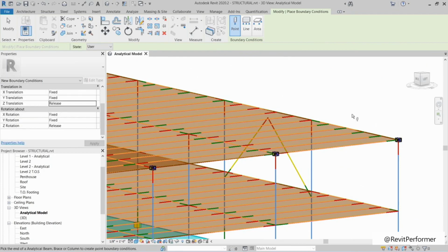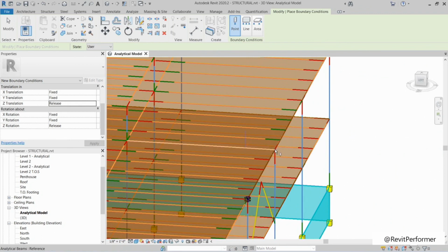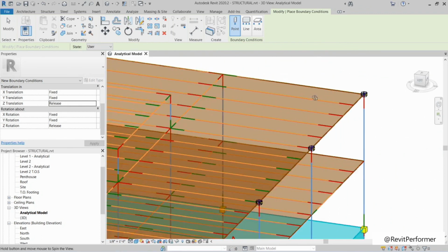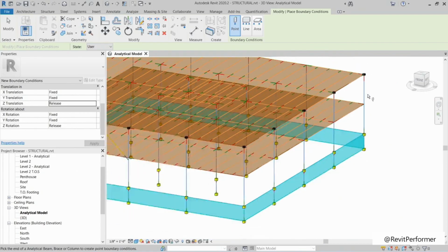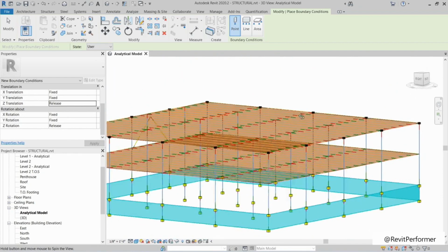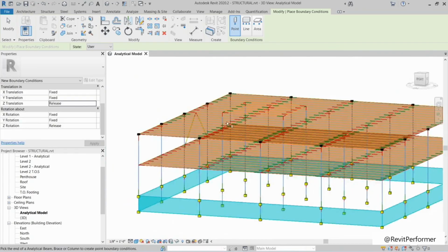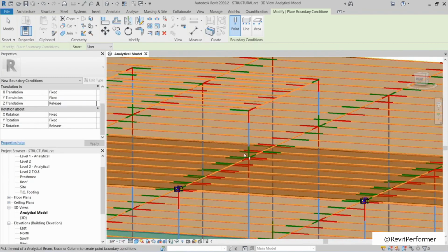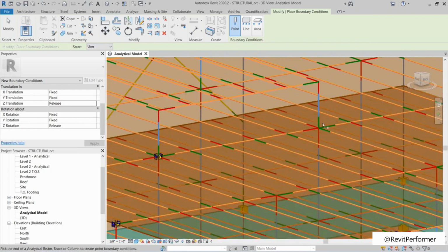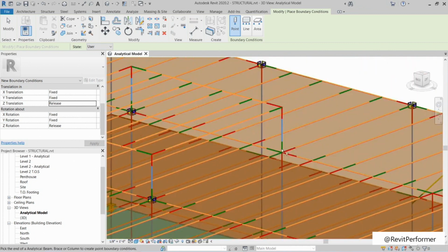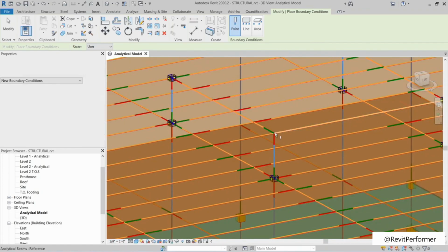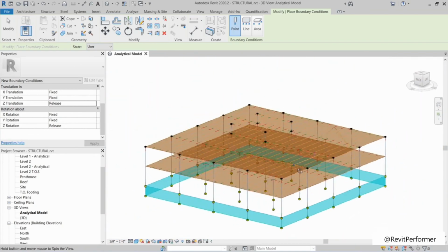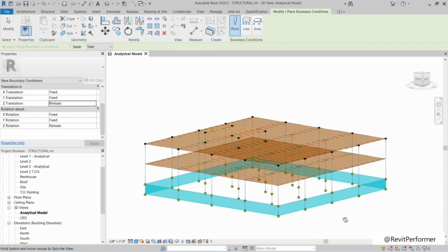Go through, we can now do the ends of all of these. We're just going to do this on the exterior. There we go. Let's do the same to our smaller columns here. Sometimes it's hard to grab them. I'll do the same to the tops of these. There we go. Now we've added all of our boundary conditions to our point loads dealing with our columns. Now that we're holding up our columns, we can go on to larger things.